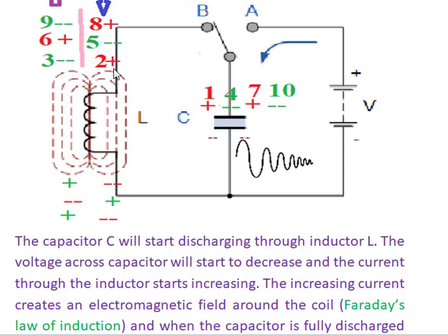See here, the current responsible for producing this magnetic field is positive here. So, the induced EMF produced by this coil on shrinking of the magnetic field is negative. Again, here negative, automatically here positive.